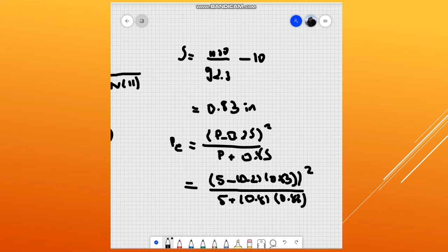When we calculate this, the direct runoff or excess rainfall in wet condition is going to be 4.13 inch. Why? Because we know that this kind of soil is almost saturated, so ponding is going to occur very fast.